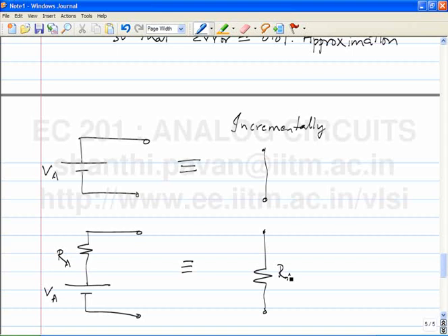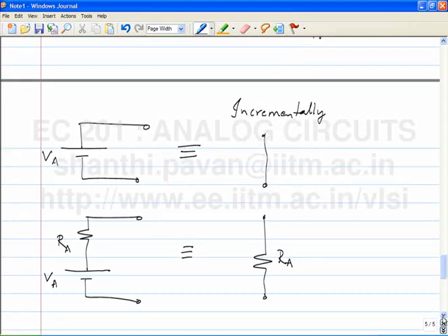Any current qualifies as a small signal because since the slope is constant, the higher order terms in the Taylor series are all zero, which basically means that there is no error incurred in approximating the voltage for a current I plus delta I by simply the first two terms of the Taylor series. You understand? Okay. So now let me take a third example.